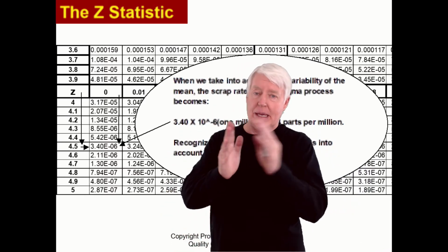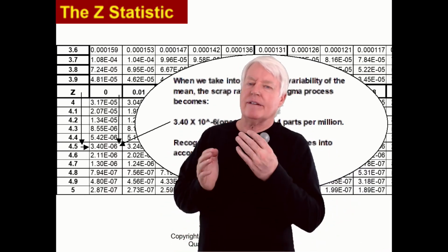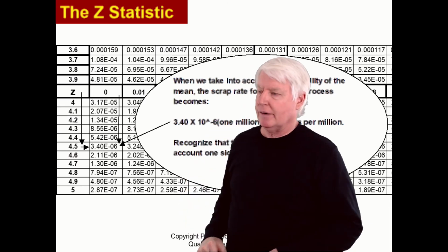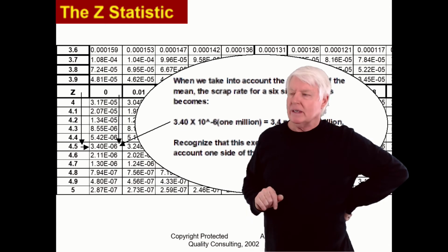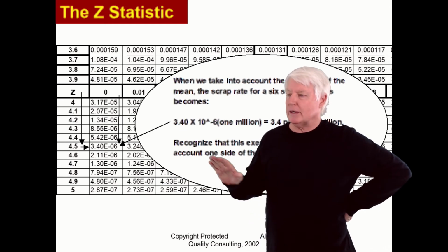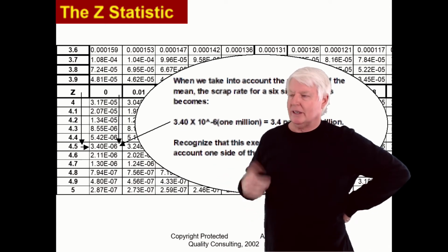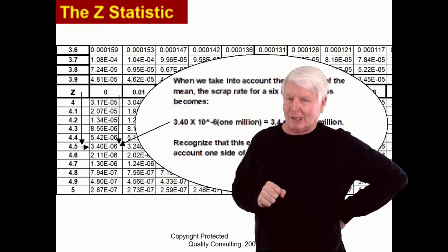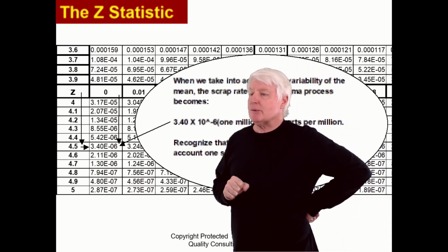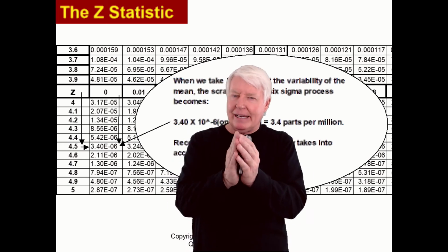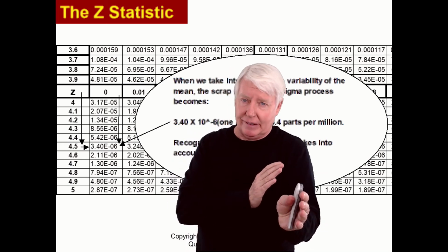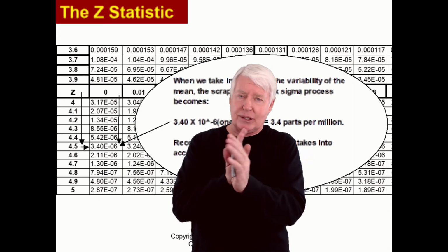Now, if you compare PPK and CPK, you can find out what the actual sigma shift is. That's what I would prefer to do. But sometimes you do need to use the 1.5 sigma assumption, which we will do in a future lecture, by the way. But generally speaking, I'd rather look at CPK and PPK and find out what the actual sigma shift is, because there will be a sigma shift.